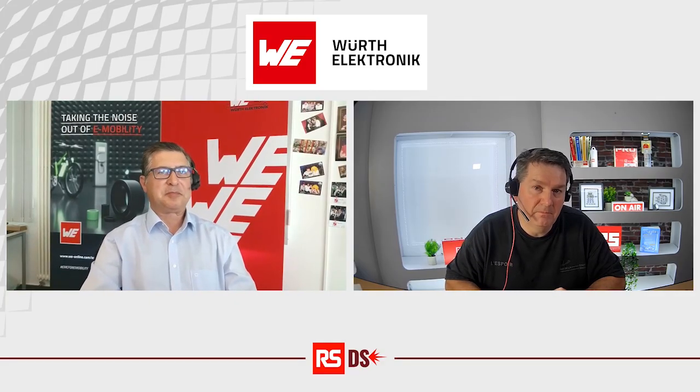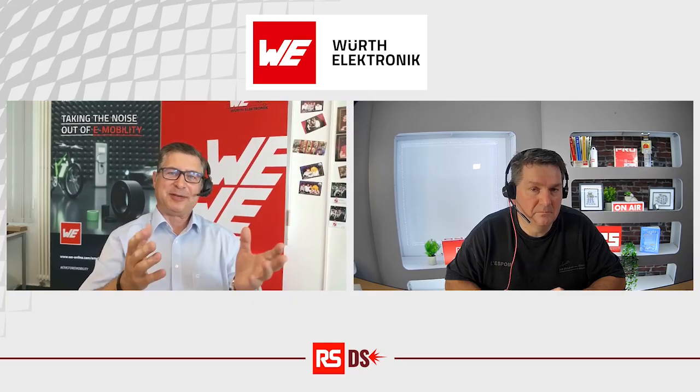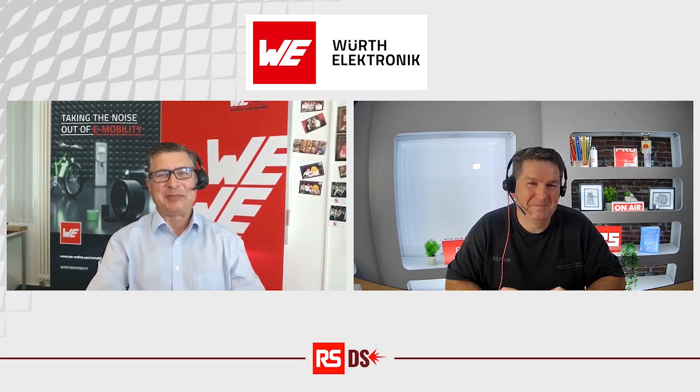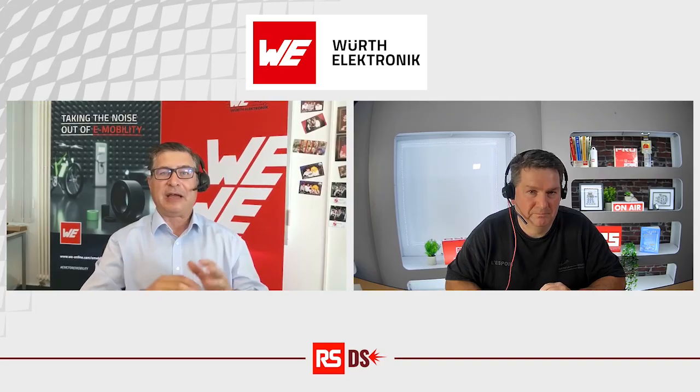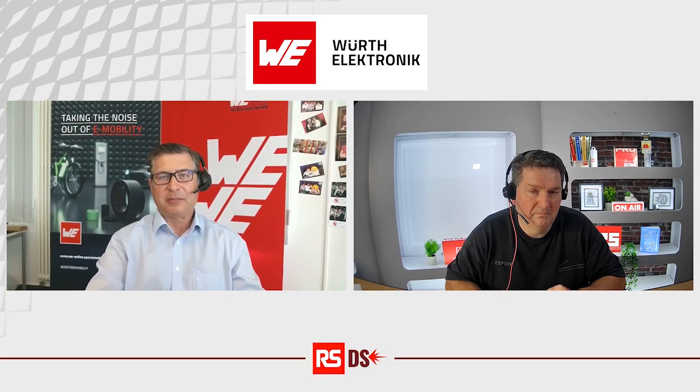First of all, I have a lot of friends who know that I'm an electronic engineer. They sometimes bring me devices to fix, telling me, Laurent, you're an electronic engineer, fix it. The first thing I look at is to change the capacitor. The capacitor is the first thing that gets damaged. They have a lifetime, especially when you apply too high ripple current to an electrolytic capacitor, they get hot, and sometimes they are broken before 2 years.